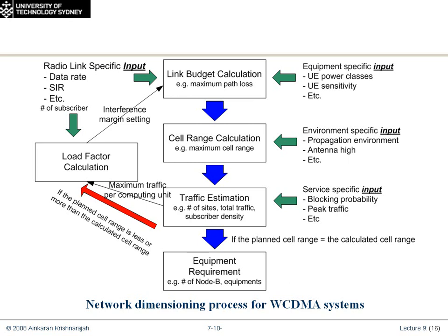And one of those calculations is what's called the path loss. So if we were to power up the base station at, say, 15 watts out of the 20 watts, how far would that signal go? It has a natural attenuation based on laws of physics, which I'm sure some of you have covered already, or it might be part of a lab. And then from there, you can calculate what the typical cell radius will be based on the path loss. That's a path loss calculation. So that's the first calculation that's actually made.